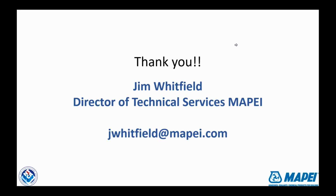I know that NTCA and the reference manual has a good document on that. Not only that, Jim, I think there are many trim manufacturers that make a trim outside corner piece that is fantastic, and that's the way I would probably recommend going. Yeah, I agree, and you certainly can have one tile overlapping the other and still have a sealant joint in there, just to accommodate expansion and contraction.